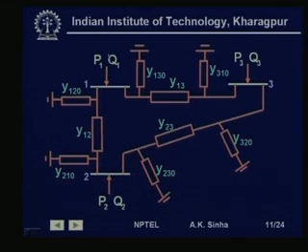Now, if we take these power injections and convert them into current injections, then having this circuit with us, we can now, using Kirchhoff's law, write the network equation for this system.